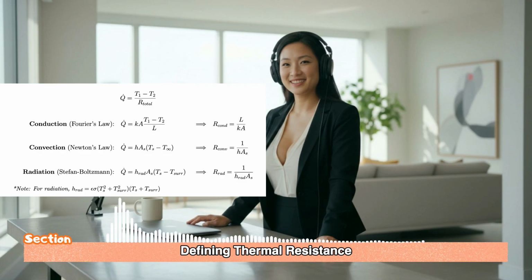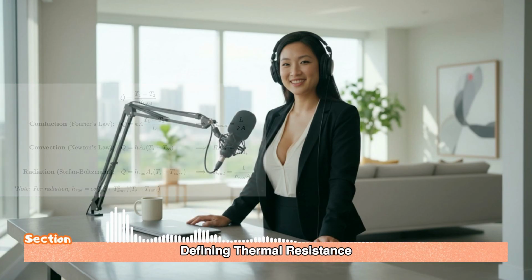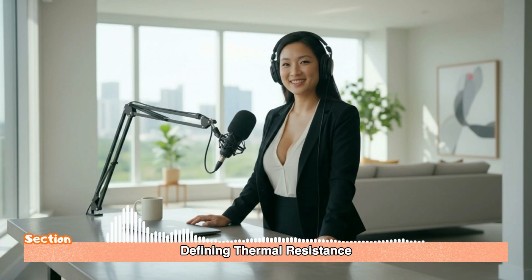And the crucial nuance here, the thing that always trips people up, is that unlike h conv, which we often assume is constant, h rad is strongly dependent on the absolute temperature. You have to use Kelvin. Yes. You can't just plug in a fixed number for h rad without thinking about the temperature range of the surfaces that are radiating. Okay, so let's put them together. A wall surface is exposed to air. Convection and radiation are happening at the same time.